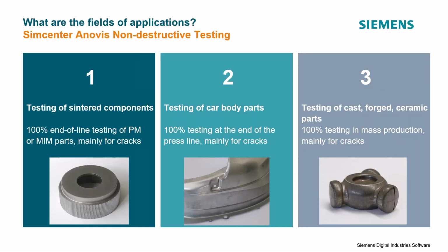And what are the things required? You need to get some response from the part. So you must be able to excite sound or vibration on it. Some geometries are not very suited for this, like a massive ball will not give you a rich spectrum. There's mainly only the breathing mode. But here you have various geometries and you get a rich spectrum and you have a way to get it excited without damaging it. And that's it.